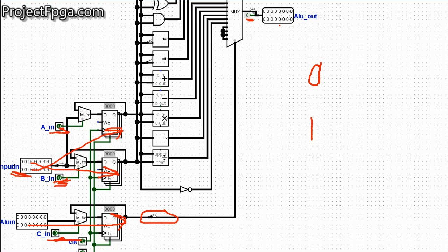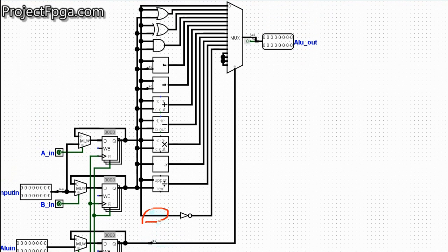That is, in case you have an overflow or maybe a negative number, and that also occurs here during the selection. The MSB is always omitted because the MSB is more like a sign bit that differentiates between an operation and a number. So here you can see only 3 down to 0 is used to work on the multiplexer. And remember about the priority. The higher the value, the higher the priority. When I'll be explaining the greater than signal, I will show you where this particular analogy is used.